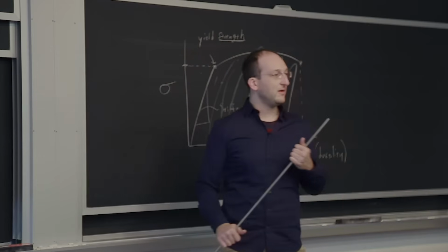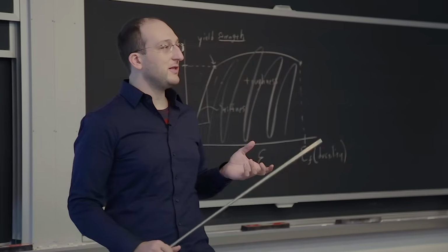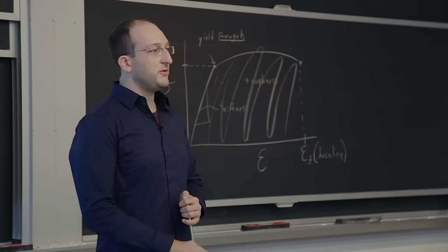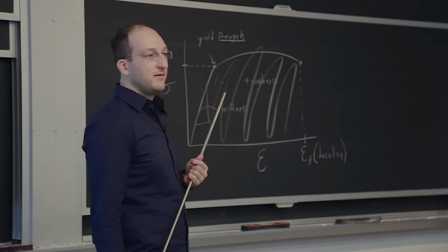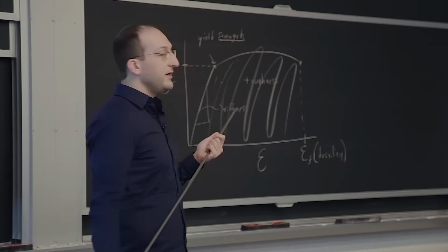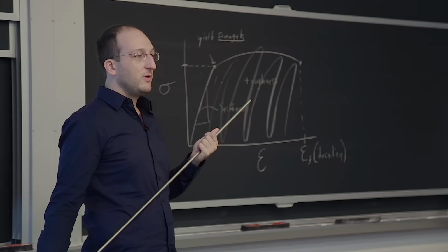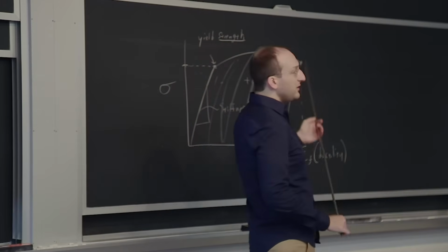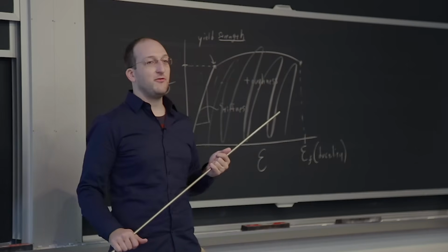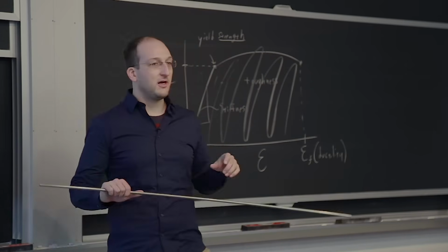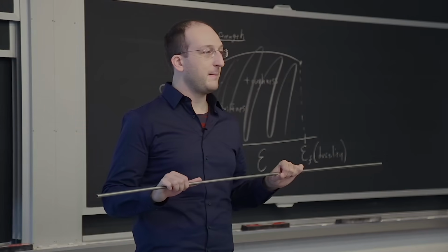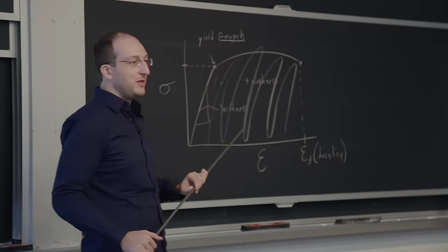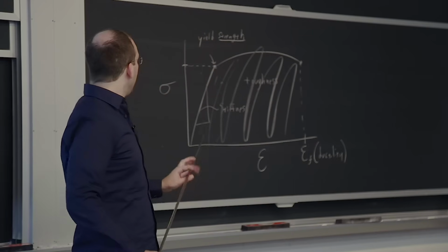But in your personal hands-on experience, does aluminum tend to fracture when you bend it a little bit? No. So then what words would you use to describe it based on this curve right here? Yep. Ductile. I would say, yep, ductile and not brittle, because you can bend it quite a bit or stretch it quite a bit before it fractures. How about stiffness? Is it really hard or really easy to get aluminum bending? Pretty easy. It's fairly easy. So would you call that stiff or compliant? Compliant, okay.